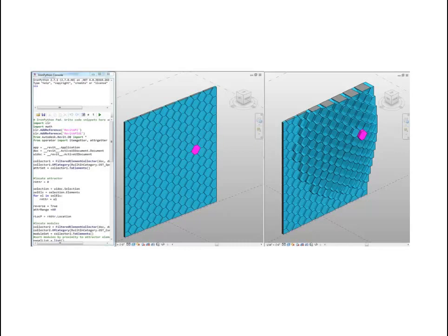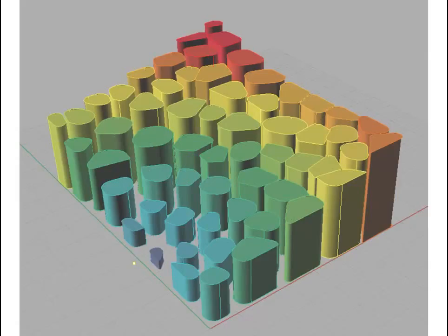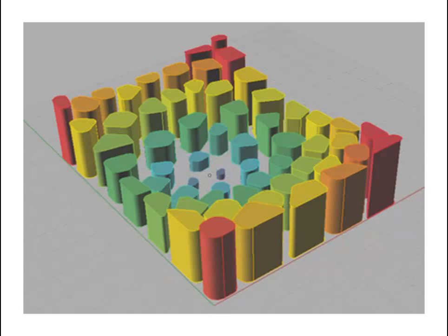So this is Revit, and this is actually taking these panels and extruding them. They're all flat, but you're extruding the outer edge of it, and that's creating that sort of facade bulge. This is extruding in the, Y, Z? X. X. There's only 3 choices. Extruding in the X. Okay. This is another example. There's some kind of Voronoi thing, and this is extruding it the opposite way. Here it's not being extruded very much. In the back it's being extruded quite a bit. Okay, and the color is actually changing in response to it as well. Okay, change the position of the piece, and change the form.